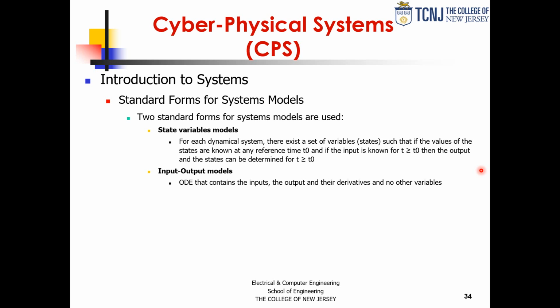Also, the state of the system is changing because the system is dynamic and is doing something useful. If the state of the system doesn't change, then it's not doing anything. It's just a nice paperweight, okay? But the state is changing. The future state is a function of the present state and the input. That description, which is a state variable description, applies to every system regardless of the complexity.